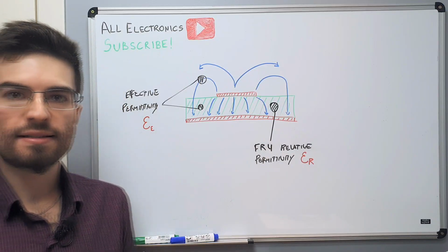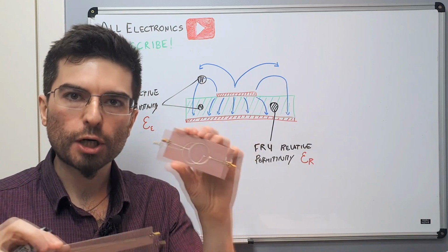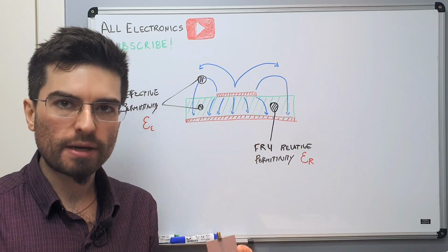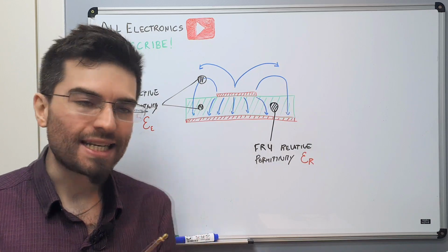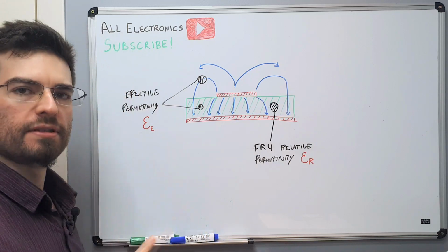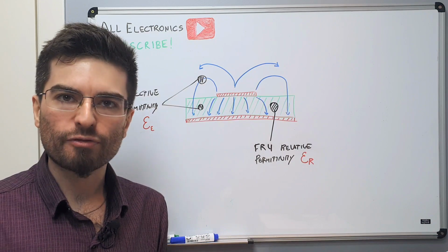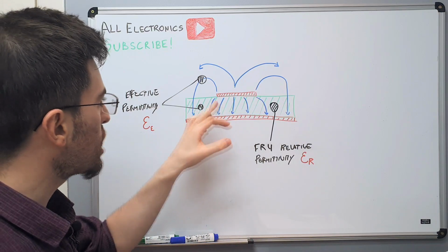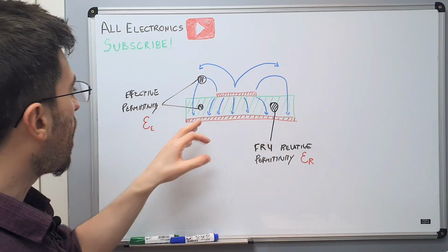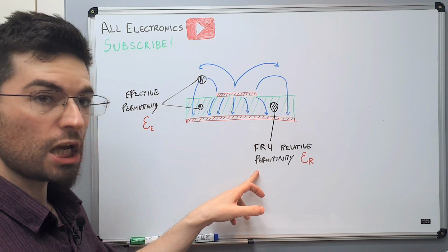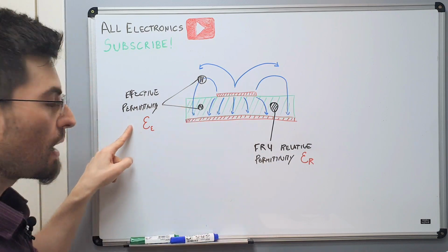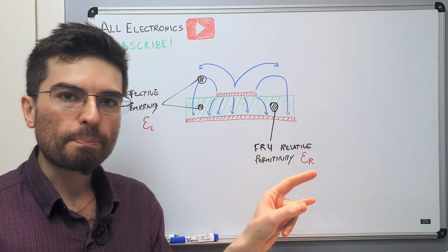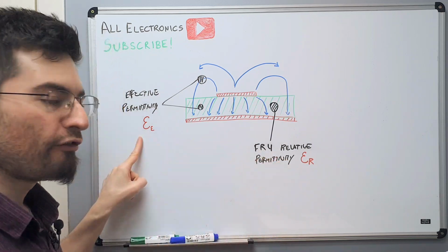Actually, for any method that we are going to use to make a real measurement, we are always measuring the effective permittivity, because we are measuring the real thing. We are always measuring the combination, for this microstrip geometry, of the material's permittivity and the air permittivity, which becomes the effective one. So after we back calculate, we have the effective permittivity.